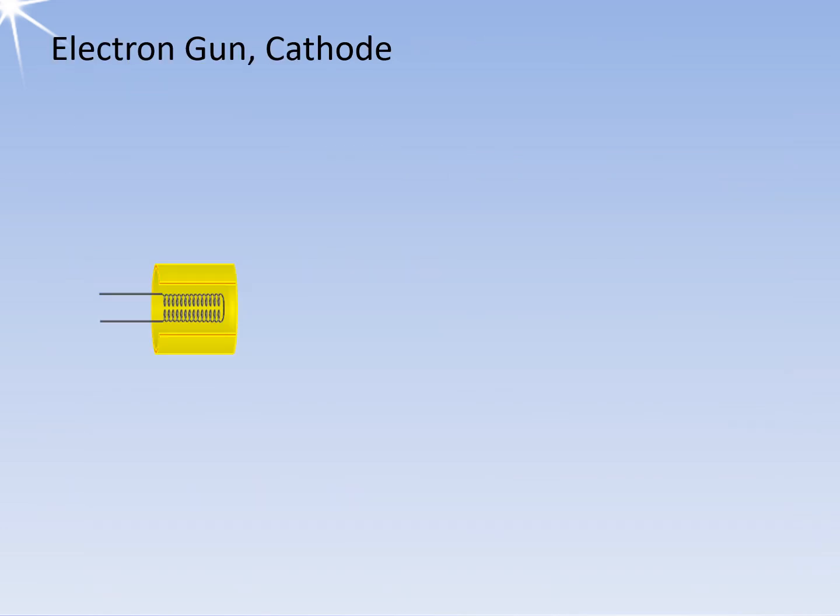The electron gun is the radiation source in cathode ray tubes. The electron gun provides a narrow, collimated electron beam with precise kinetic energy. The core of the electron gun is the cathode. This is usually a cylindrical body whose surface is covered with barium oxide for better electron emission. The cathode is charged up to several 100 kV. In Klystrons, this voltage is referred to as the beam voltage.